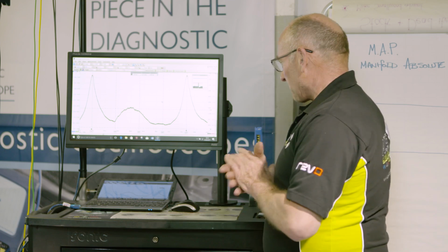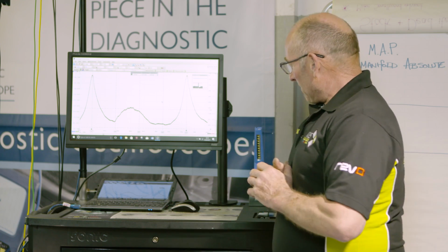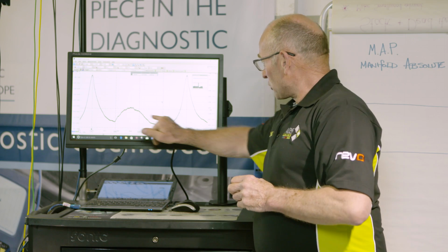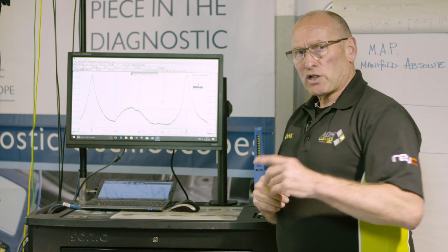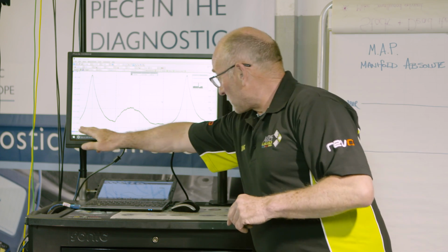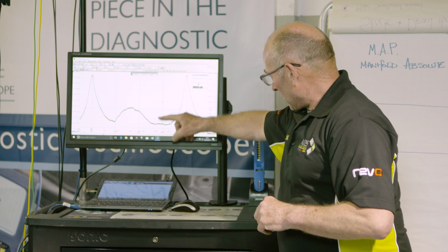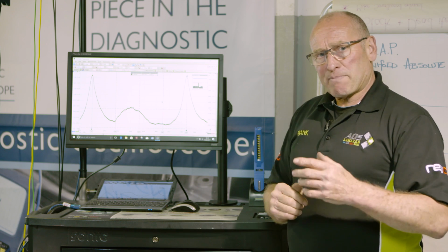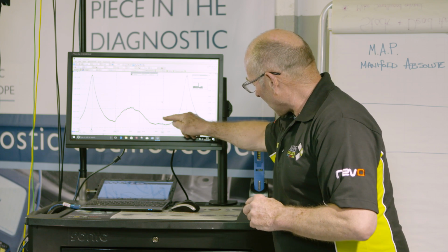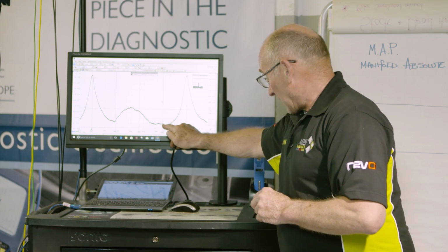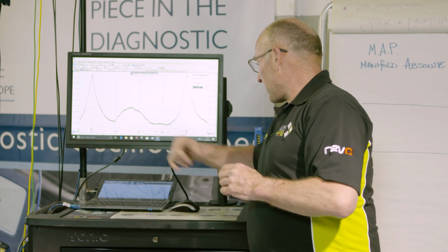We'll take some measurements of that, because normally we measure these events with a vacuum gauge, and we would expect the lower the reading, the more healthy. There's absolute zero, and we're never going to meet absolute zero. That's 1,000 millibar. We expect around 300 millibar, thereabouts. Obviously, that's 1,000, half is 500. It's looking healthy, but we'll measure it afterwards and get an actual figure for this period here.